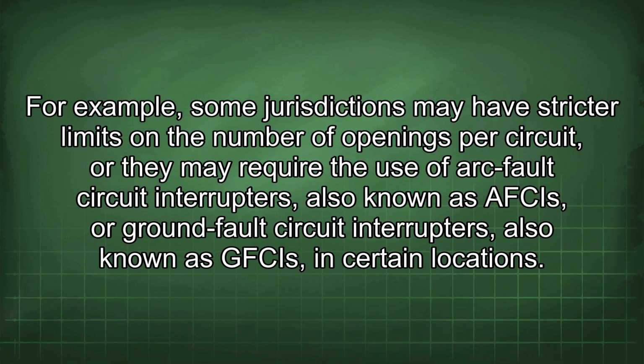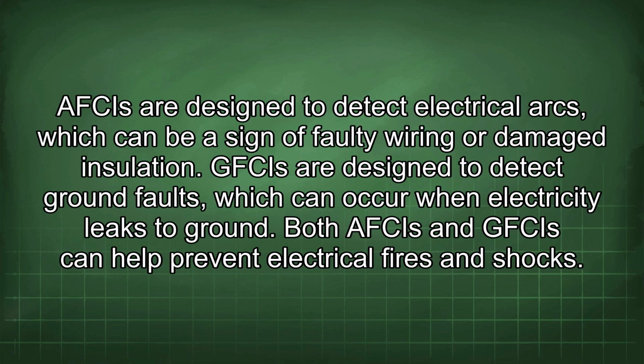certain locations. AFCIs are designed to detect electrical arcs, which can be a sign of faulty wiring or damaged insulation. GFCIs are designed to detect ground faults, which can occur when electricity leaks to ground. Both AFCIs and GFCIs can help prevent electrical fires and shocks.